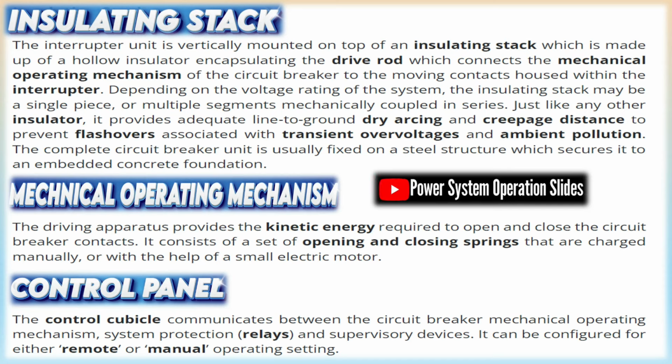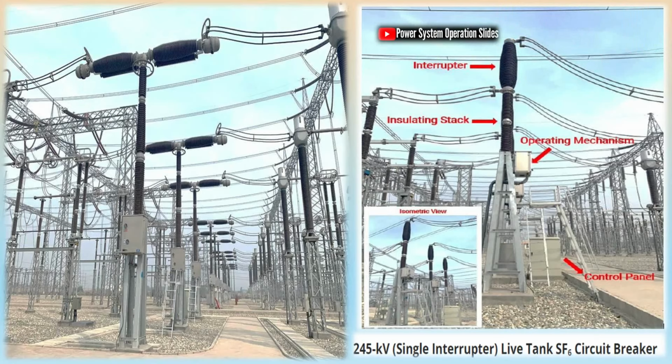The movement of the puffer cylinder against the stationary piston leads to a decrease in the puffer cylinder's internal volume, which causes compression of the SF6 gas inside the cylinder. Due to contact overlap, gas compression starts before any contacts open.